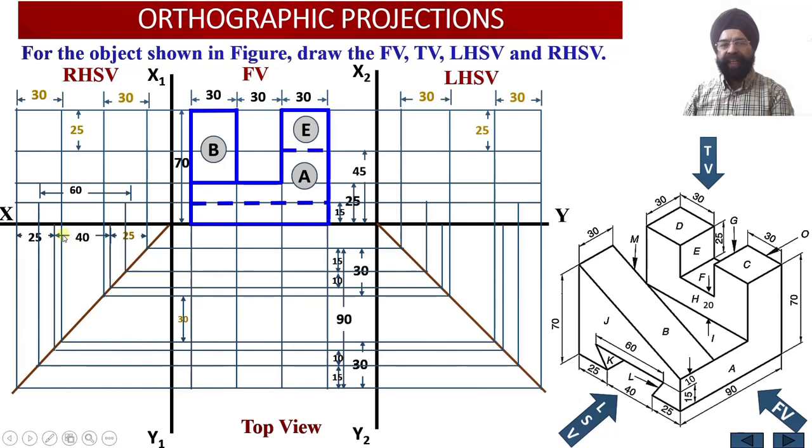And we can check that corresponding to the base, the distance happens to be 40 millimeter between the two base points of the slot. Please check, this is equal to 40 millimeter. And corresponding to the top points of the slot, the distance happens to be 60 millimeter. So this distance corresponding to the top points of the slot will be 60 millimeter, right?